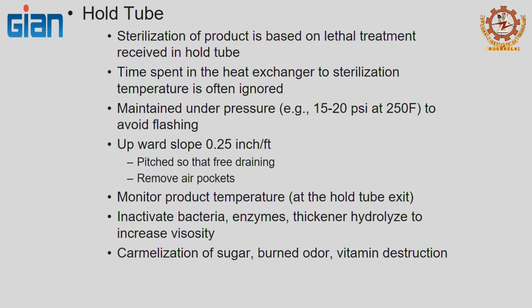Holding tube. At the heart of aseptic processing is the holding tube, because this is the place where you determine or demonstrate the lethality of your product. It does not matter how much time the product spent in the heat exchanger; you do not consider the lethal effect, only the time it spent in the holding tube. So 30 seconds, 50 seconds, whatever it is based on your design, that is what is considered.